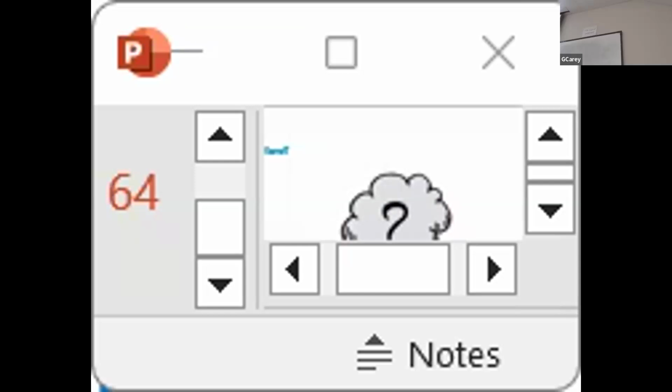Well, what the variable speed would be like, I'm showing 3, make it 75. And one of them has, or maybe they're all, and we're just saying, hey, a far reaching one, as he's reducing down, I don't want him to get down to 0. I want to make sure that I can reach that furthest terminal unit, furthest point, and overcome the pressure drop of the control valve in the terminal unit.